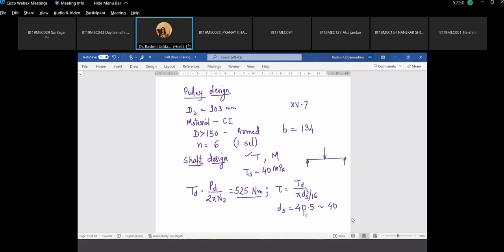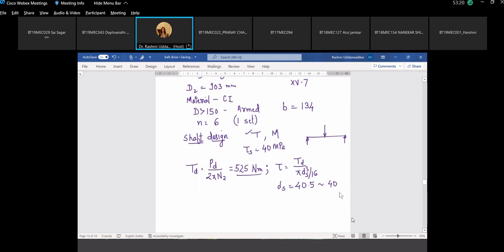So if this value is coming out to be 43 or anything above 43, then going to 45 is good. Otherwise, for this small change, 0.5 mm higher than this required standard value, moving to the 45 mm diameter makes more material, more weight, and increases the cost of bearing. Okay, so we'll go with shaft diameter 40, and go for the hub design.